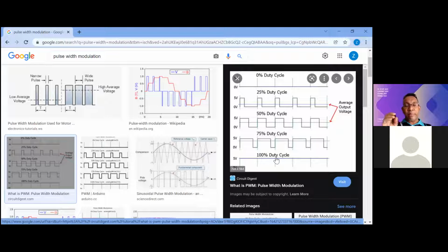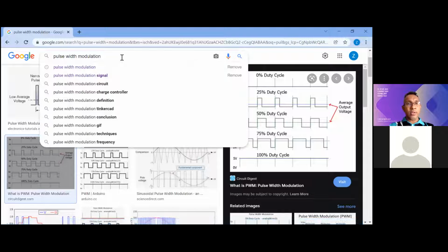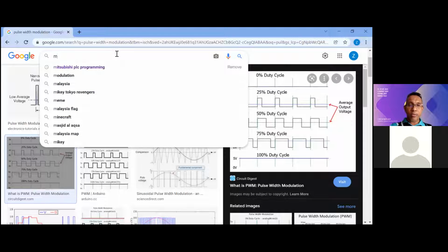Okay. So maybe you wonder, you ask a question, how to control the speed as well, instead of only on. Yes. So they use this term to control the speed, percentage of duty cycle. Okay, I think this one answers your question. Pulse width modulation is the signal used inside the motor, but to control this signal in the controller, the DC motor connects to Arduino.